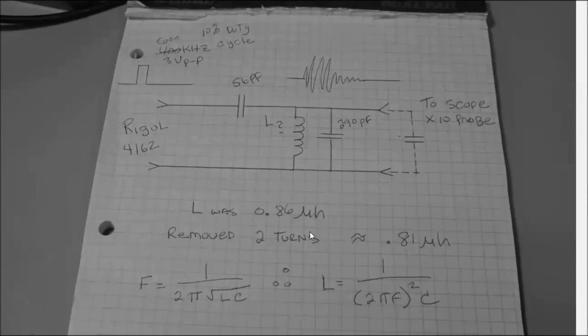Alright, so what we've learned today is that we can take a tuned circuit, like the parallel resonant circuit here, with an unknown inductor, energize that circuit with a short duration pulse, cause a ringing oscillation at the resonant frequency, and measure that frequency, and then use your formulas or your app or website, whatever, to calculate the inductance.